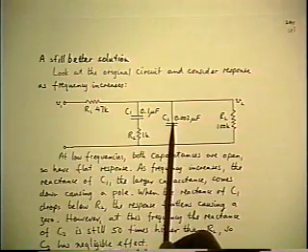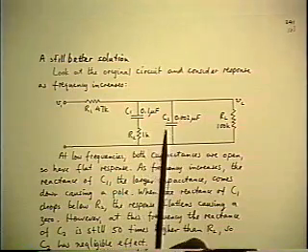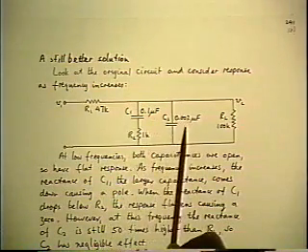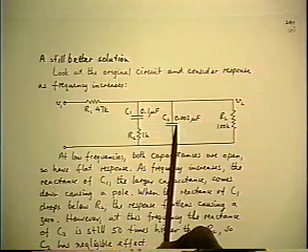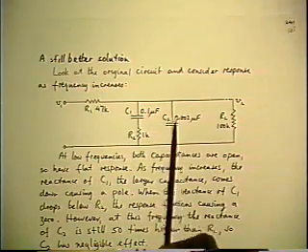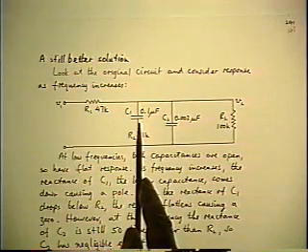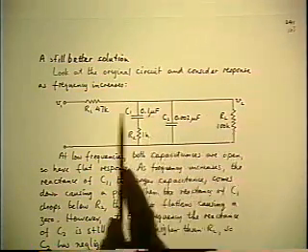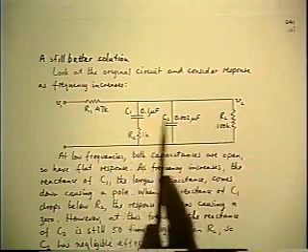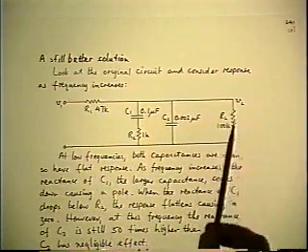So you could throw it out, which is equivalent to dumping the second part of that middle coefficient, based on the same approximation, which I already mentioned is less than a 2% error. So forget C2 while the reactance of C1 comes down. Now, as it comes down to be comparable with R1 and RL, of course, it's going to start bypassing the RL, so the 0 frequency flat gain is going to start dropping off. So there's going to be a pole somewhere because of the C1, C2 being negligible.